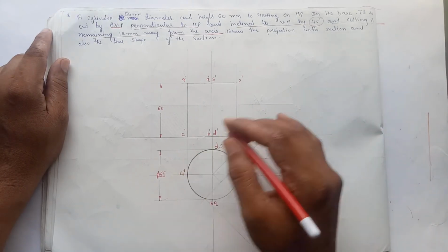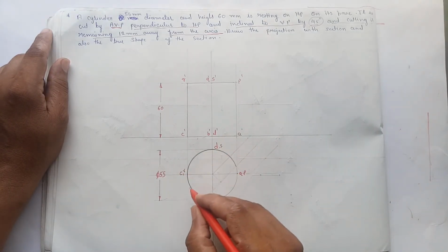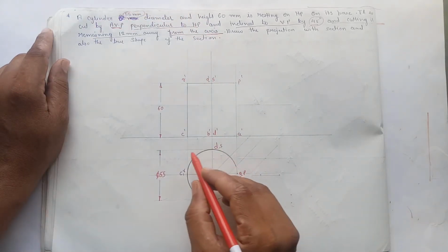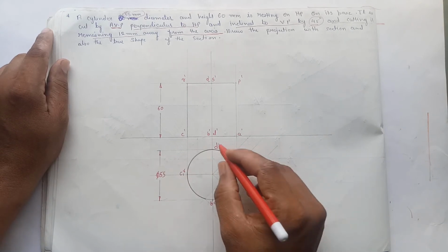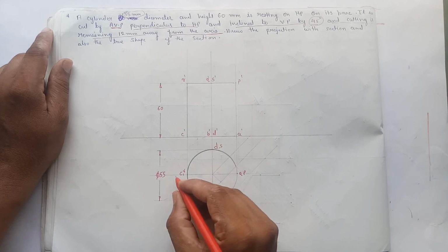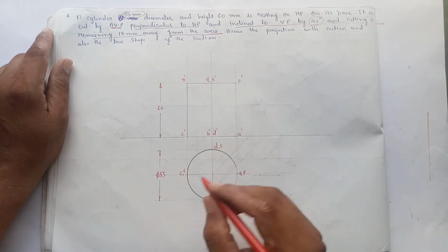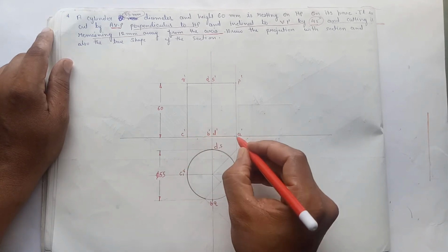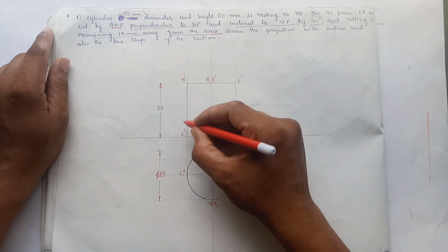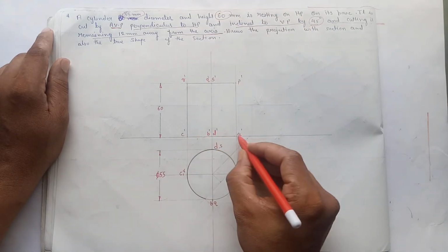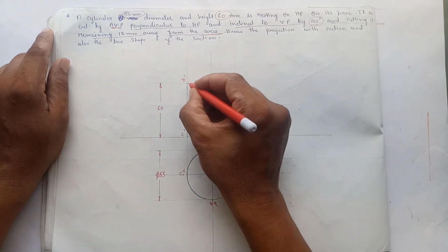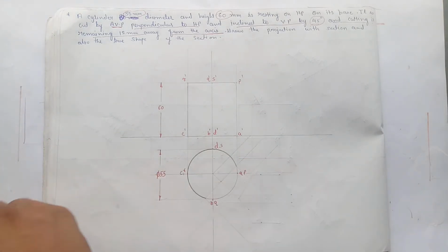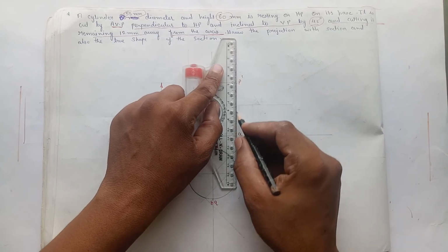So now first of all draw the front view and top view of the cylinder. So this will be the top view of the cylinder. The diameter of the circle is 50 mm, the base circle diameter. Draw the base. Here I have shown only 4 divisions. A, B, C, D is the base and P, Q, R, S is the top face. Now project A, B, D and C. This will be the base. And now measure the axis height, which is 60 mm, and draw the top face, P dash, Q dash, R dash, S dash. So this will be the front view and top view of the cylinder.